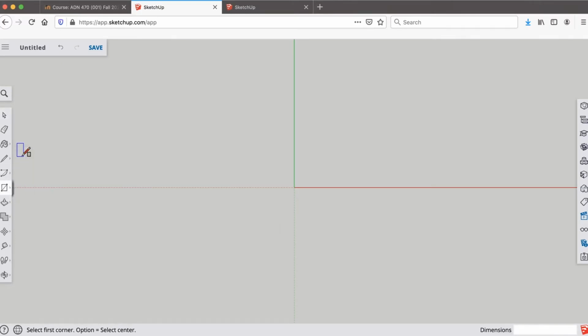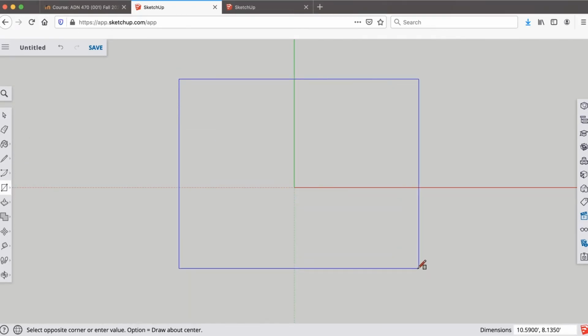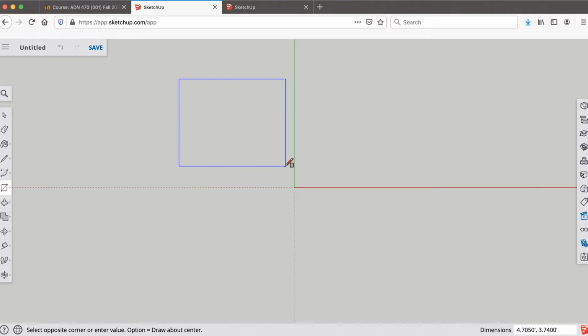So you're going to come here, little rectangle tool, and you just click once. And you see the numbers change on the right hand bottom. Super fantastic. And this is why I like SketchUp. Even though you could do this very easily in Illustrator, the precision in SketchUp is awesome, and also having that live number. So in order to make my square, you can click again, right? And it's going to make whatever dimensions I click on. But that's not actually what I want. If you click once and then you type in your dimensions, it's going to make that exact measurement.